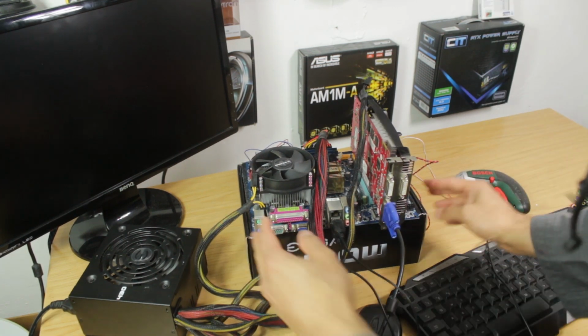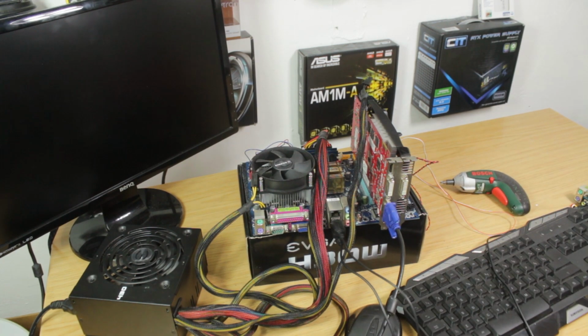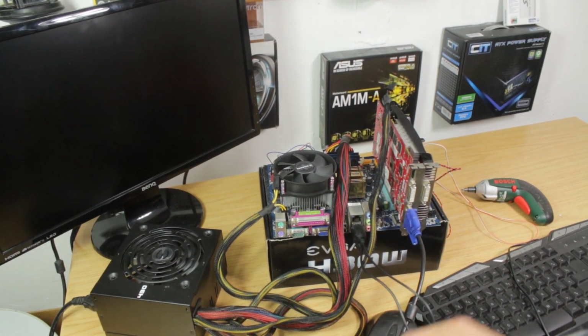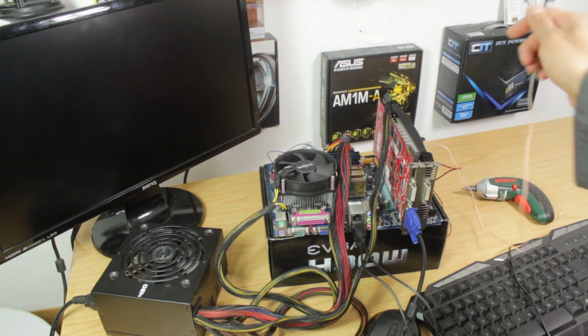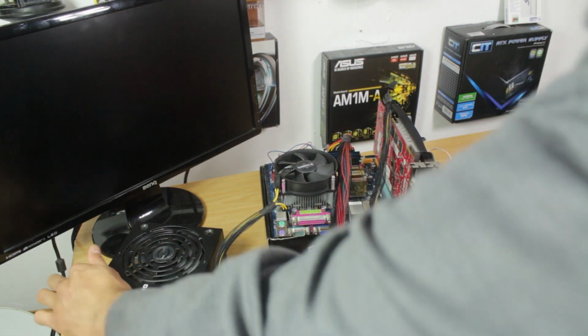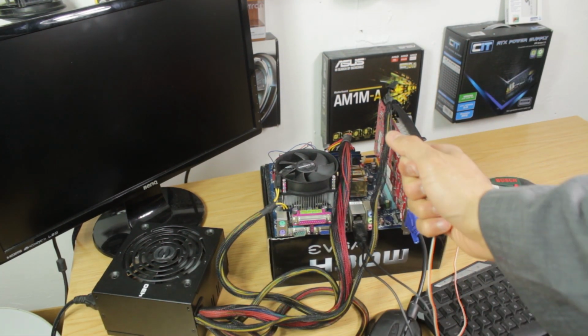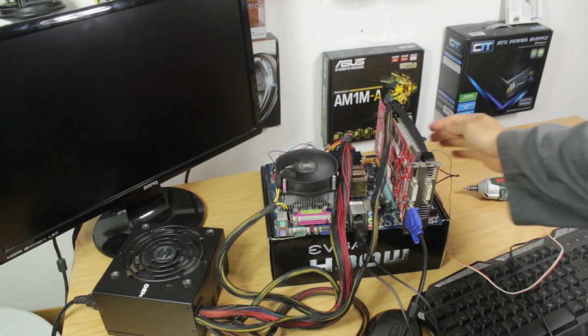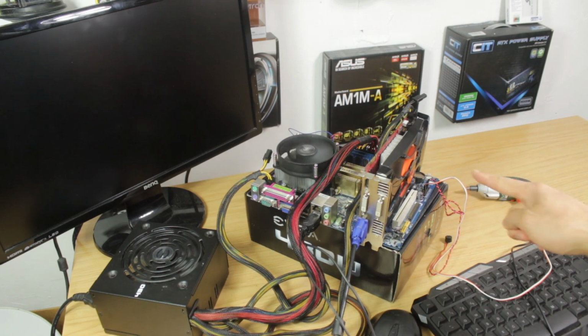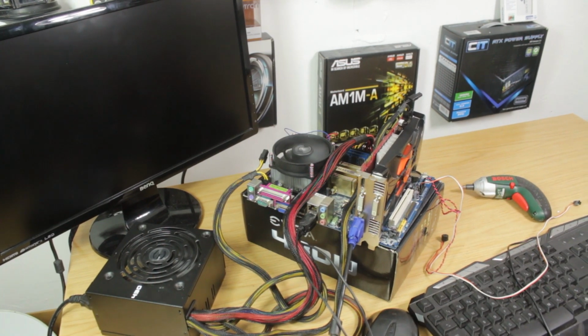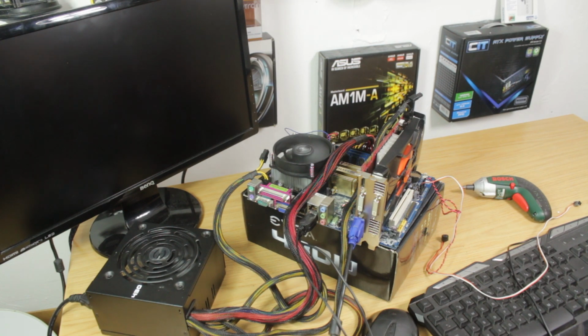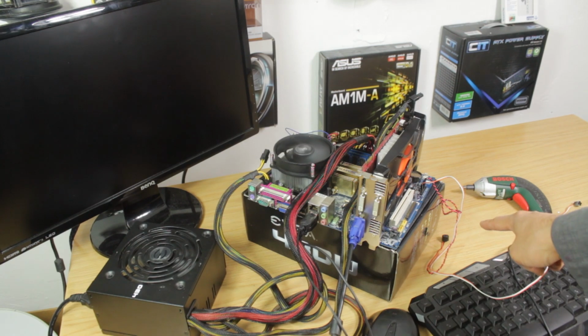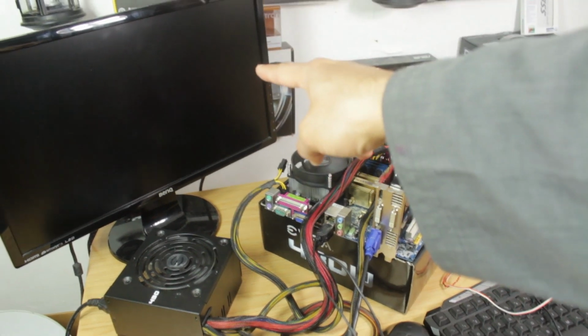All right, so let me just check that. So yeah, okay, that wasn't too bad. All right, then, so turn the power switch on, and we're going to turn the whole thing on. There you go. Fan spinning, GPU fan spinning. Let's wait for the speaker cable to give us any beep. We can wait as long as you want, but I have done this test and no beep is coming from the speaker cable and nothing on the display.